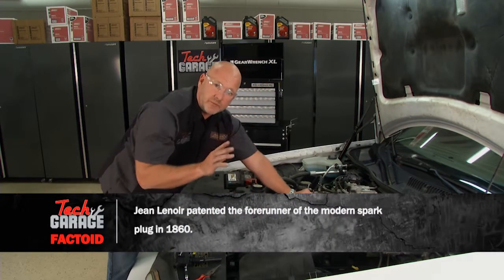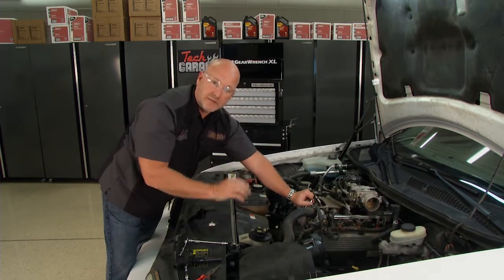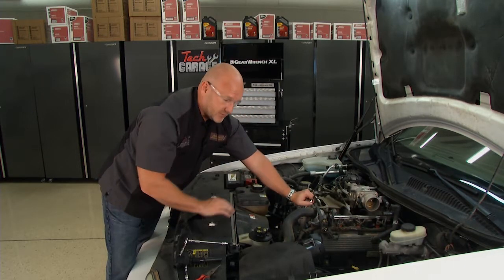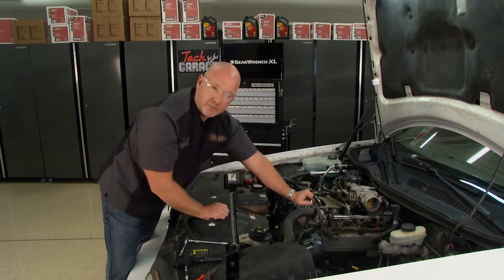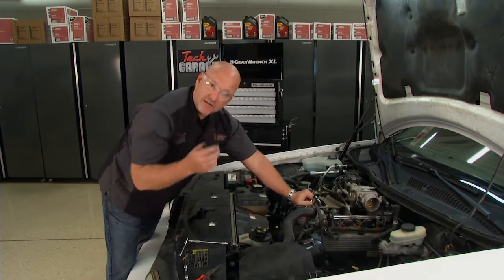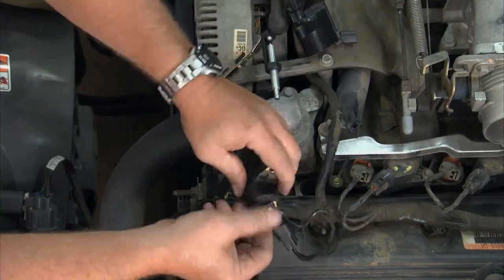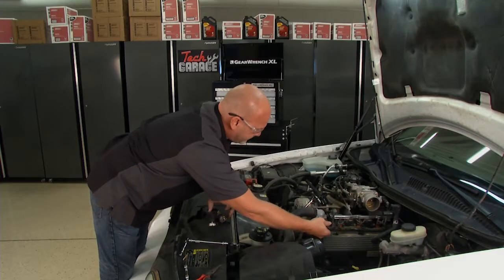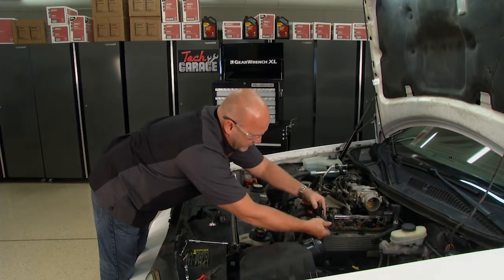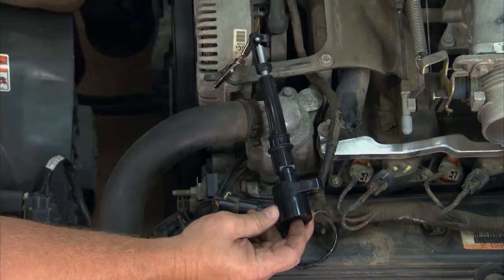Now, here's what a lot of people do. You run to your local auto parts, you get one ignition coil pack, and you think you're in good shape. But this is a great opportunity to test it with a neighboring coil pack, maybe cylinder number 4. I happen to be lucky and have one of them in my toolbox, so I'm going to rerun the test with the exact same coil pack and see what we get. Primary comes off, primary goes on, listen for the clip, you got a good connection, reinsert it on the tester.